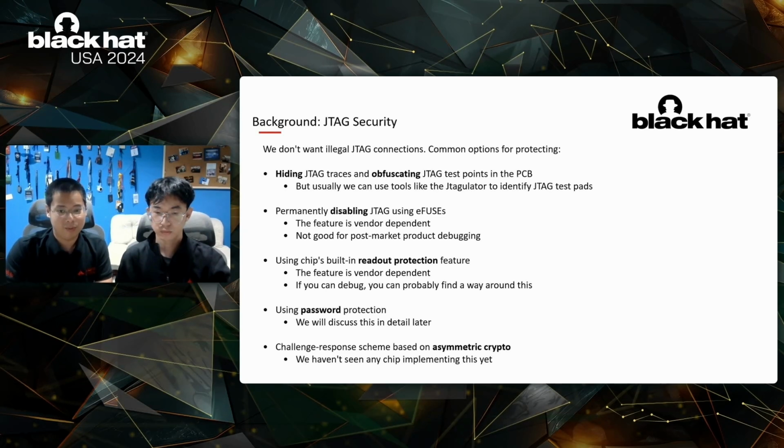Some chips, for example, the STM32 series MCU, they provide a separate readout protection feature, where a flash read via the debug port is disabled. However, this feature is also vendor dependent. Some other chips do not have the functionality. Also, if a determined hardware attacker can connect to the debug port, he can probably also find ways around those restrictions. So securing the debug port itself is usually done using password authentication, as in the case in SPC58 series,